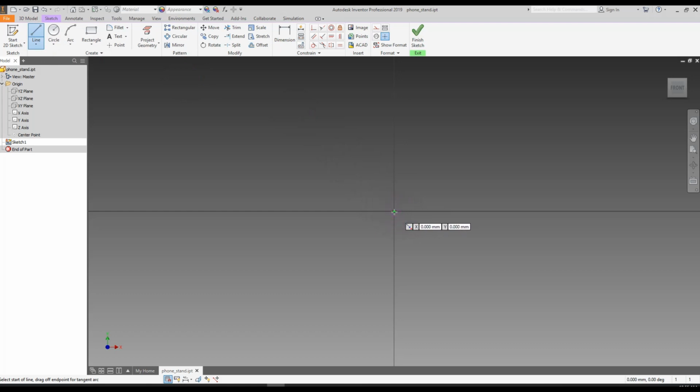When you hover over the origin, it will light up. Always try to connect your sketch to the origin if you can, at least your very first sketch, because that will make a rigid, good, rugged sketch. So let's click on the origin and then just draw out the line. Actually, we can go to the left. And then don't worry about the exact dimension.